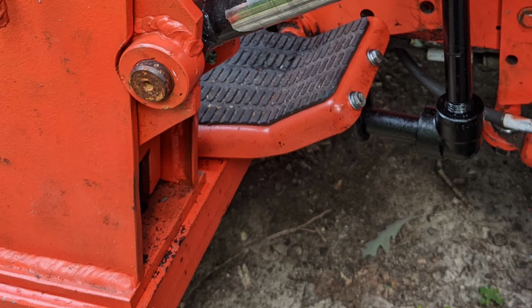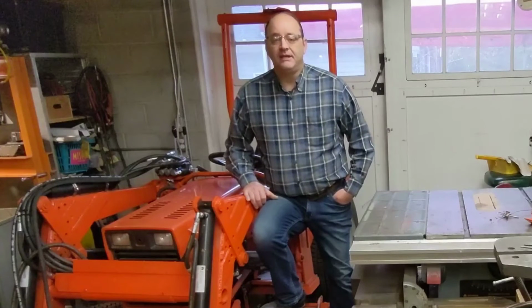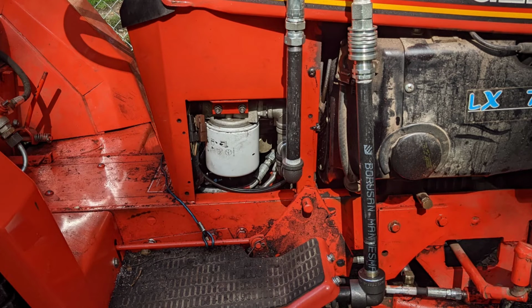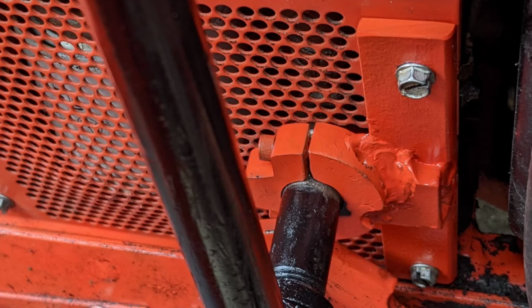The steel pipe will be routed out under the footrest, but above the loader crossmember. The relatively heavy steel pipe has enough inherent physical strength to support the free-floating quick disconnect without an additional support bracket. But on the return side, I will manufacture a support bracket that will be bolted onto the tower and clamp onto and stabilize the return side pipe.